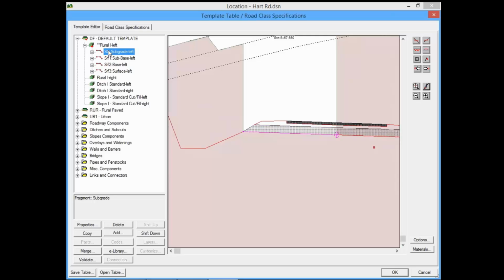When you actually construct it, you're not going to do just the roadway and just the ditch. You'll do the subgrade for the whole thing. But for the sake of the software, it does them one component at a time. And so I've cut the subgrade, then I apply this material on top, and I've got some fill material.